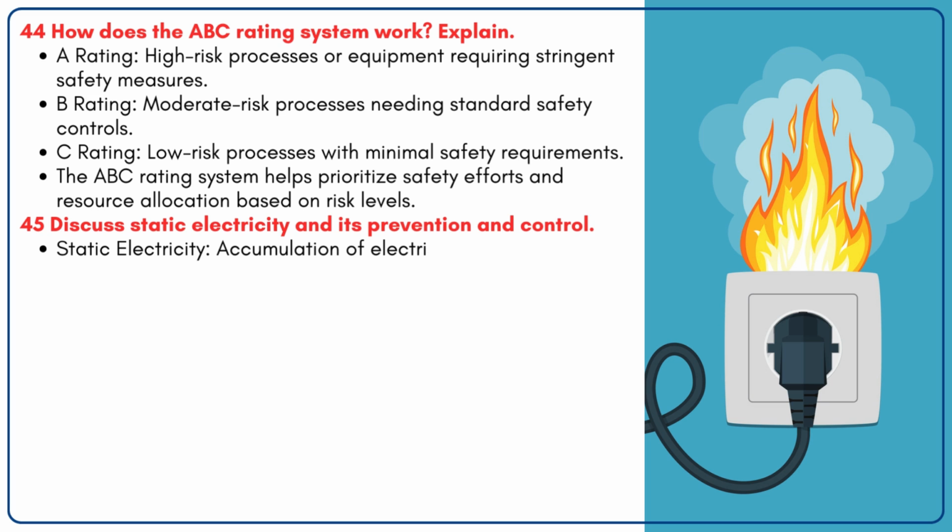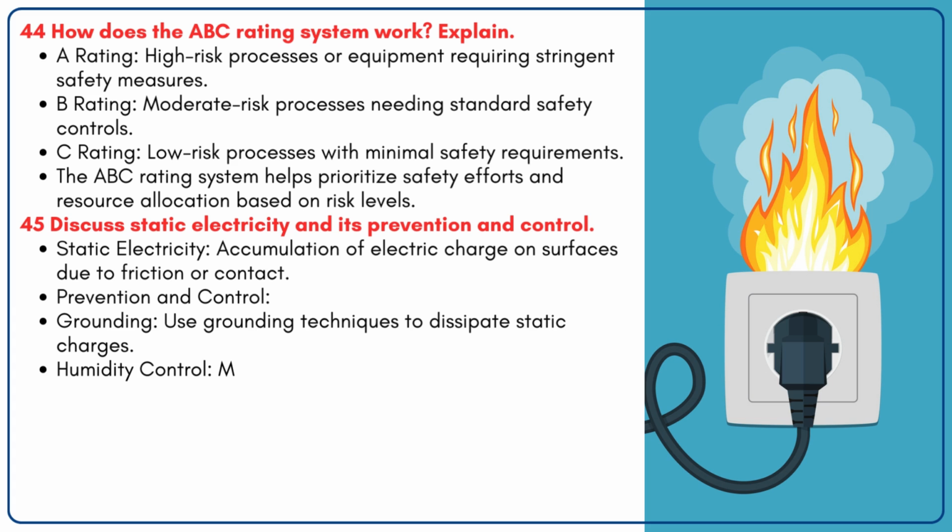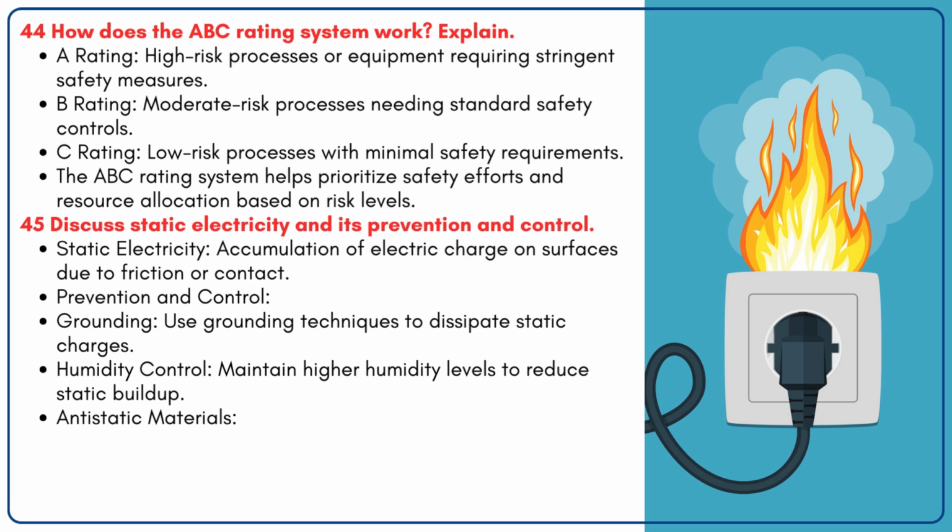Static electricity, accumulation of electric charge on surfaces due to friction or contact. Prevention and control. Grounding, use grounding techniques to dissipate static charges. Humidity control, maintain higher humidity levels to reduce static buildup.